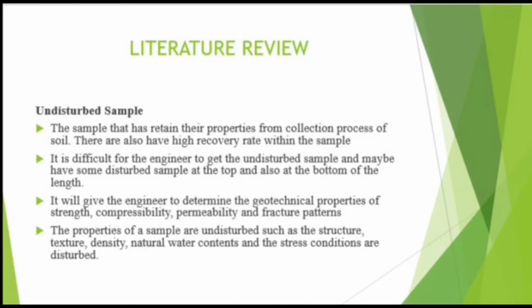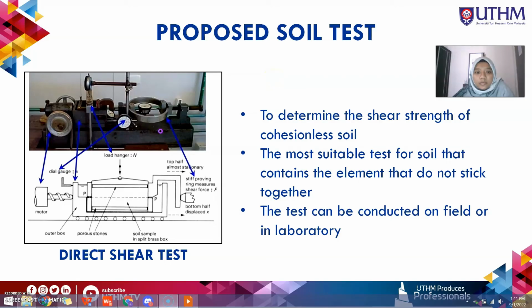It allows the engineer to determine the geotechnical properties of strength, compressibility, permeability, and also fracture pattern. The properties of a sample are undisturbed when the structure, texture, density, natural water content, and also the stress condition are retained.